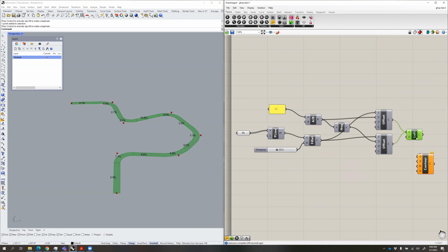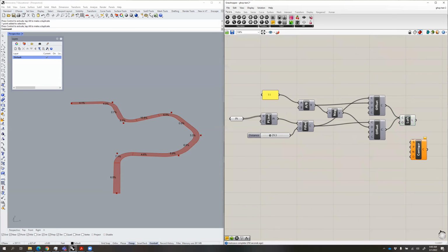And then what you can do is you can take this surface right here. You can plug that into the S, which is asking for the surface to cut contours from. It's asking for a starting point and automatically defaults to a 0, 0, 0 starting point, which is good. That just basically means it's starting from the 0 origin. It's going to ask for a normal direction, and it always defaults to the vertical normal. Basically, when it says 0, 0, 1, that means it's the vertical Z direction.